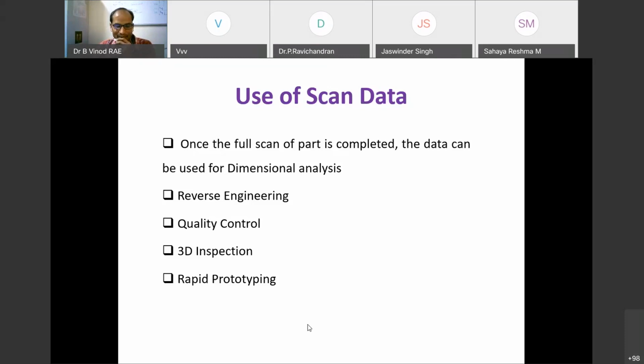Like that, the medical imaging process will happen. The doctors will give the CT scan data. From the CT scan data, we will also extract the STL file format. This STL file is put into the 3D printing machine. It starts printing from the bottom layer to the top layer. Finally, we get the whole part.